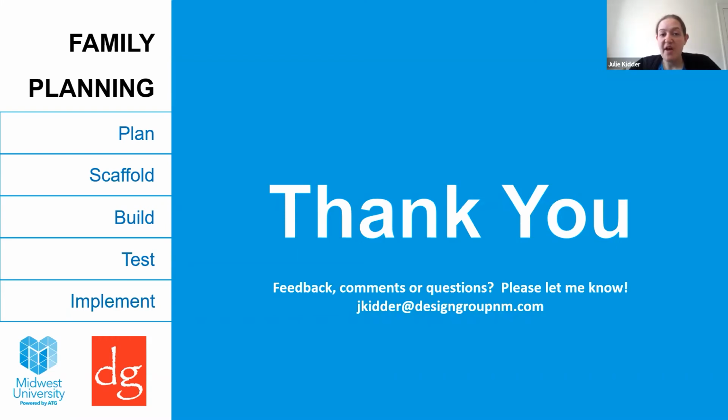So the first question is, how do you determine whether it's a family parameter or a shared parameter? Shared parameters are anything that needs to appear in tags, or that might need to appear in tags. It's also anything where I need consistent information across several families. So most of the parameters that appear in the schedules are going to be shared parameters, because I have multiple families that need that information, and I need it to be identical across the board.